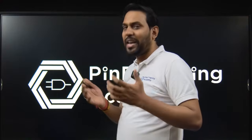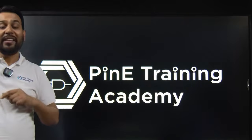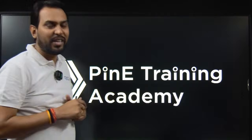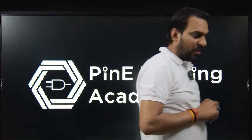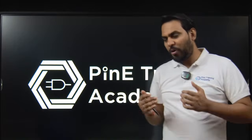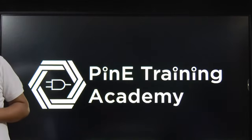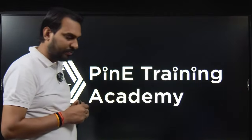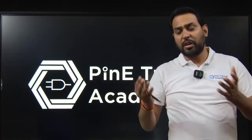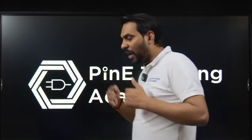A voltage controlled current source is just like a MOSFET. You have an input voltage and you find gm·VGS. The gm·VGS behaves like a voltage controlled current source. So this is the way you can describe it. Then we talk about current controlled current source and current controlled voltage source. We have voltage controlled current source, voltage controlled voltage source, current controlled current source, everything, and as per the requirement we can use them.